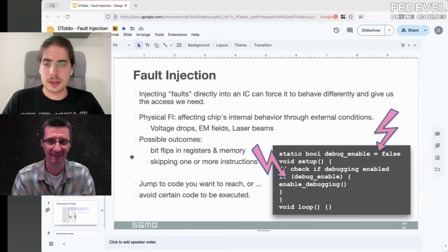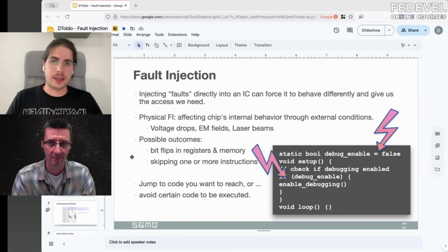For instance, in any case where you can get code or part of the code, it could make it easier for attackers. So let's say Espressif ESP32 chips, you can hack their bootloader even if you don't know the firmware that's running on it, because the bootloader is in part on GitHub, or you can get it from a different device and analyze it, and then you can know the timings.